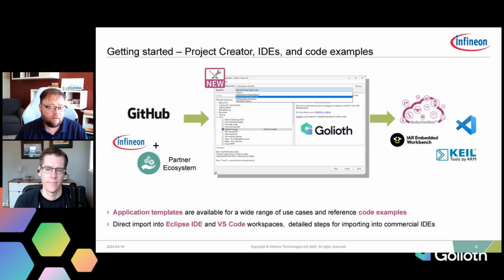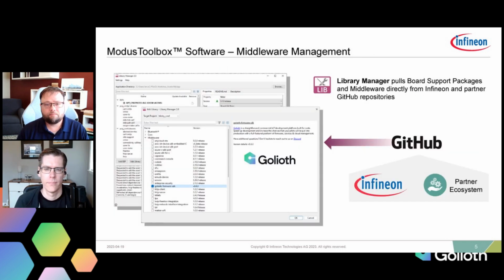For ones like the IAR and Keil, there were steps to be able to use their specific project connector files to import those into those IDEs. Now, once you're in the IDE and you're working with it, you may need to add some additional behaviors or modify that. So that's another key utility I wanted to talk about, the library manager.